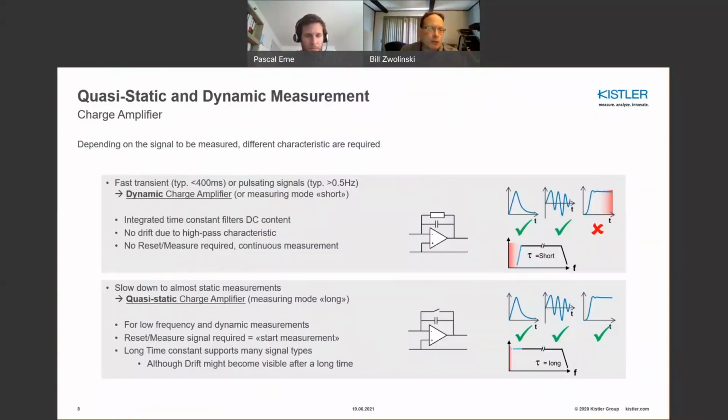So there's more terminology, quasi-static and dynamic. Well, there are amplifiers that just measure dynamic only, okay? A lot of times those are used in vibration analysis, vibration measurement, and they're very, very useful, very much rangeable, all the features that I talked about previously. Then there's a special class of amplifier that's both quasi-static and dynamic, which means that it can measure the low frequency characteristic as well as the high frequency. And what that does is it allows you to now use quartz technology that you can optimize on a quasi-static solution in addition to the dynamic.